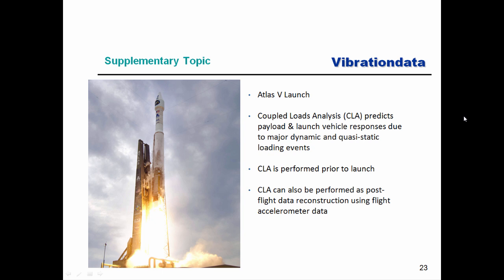And this is performed prior to launch. Now, after the launch, hopefully we've gathered flight accelerometer data, and we can take that data and feed it back into our coupled loads analysis and do a post-flight data reconstruction. And we can use that for a variety of reasons. We can use it maybe for updating models, both for forcing functions as well as the response of the vehicle.